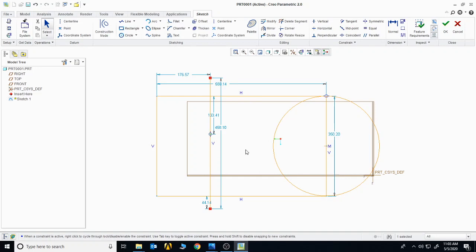And if certain dimensions aren't given, let's suppose I'm not given the dimension of this side, so what I will do is click on the normal, this point, and move to the right and click on the scroller. So you can see that you have generated your own dimensions. Now you can modify it accordingly.